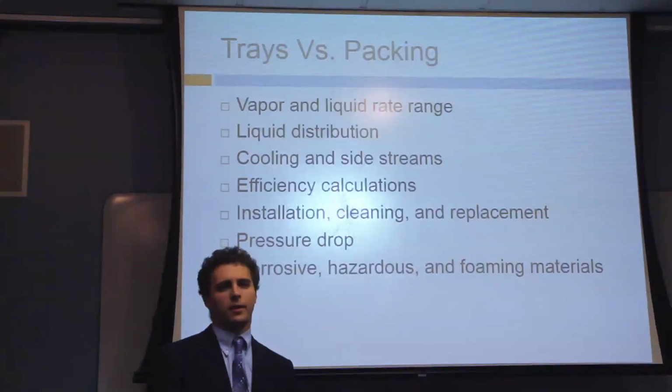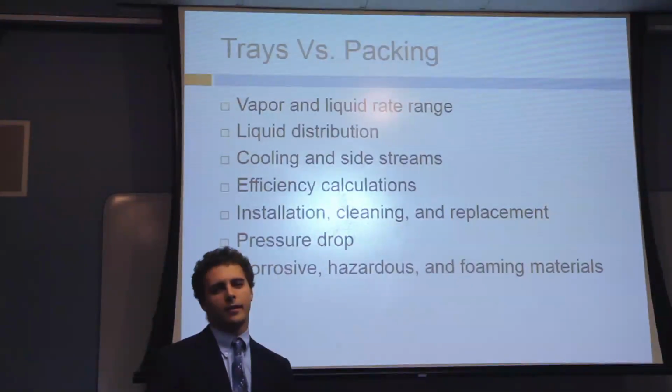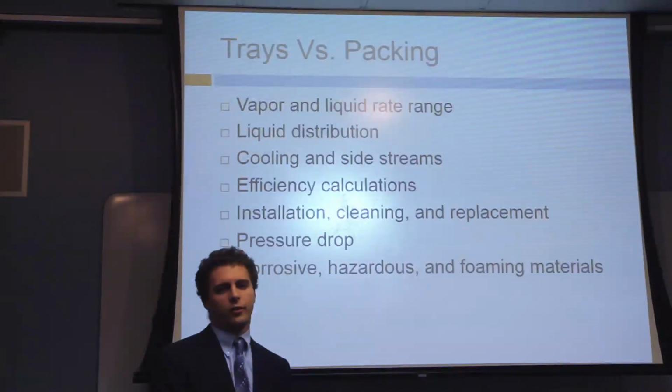They work well with hazardous liquids because of the shorter liquid holdup, which makes it easier to provide for safety measures. The packed columns also work relatively well with foaming materials compared to trays.